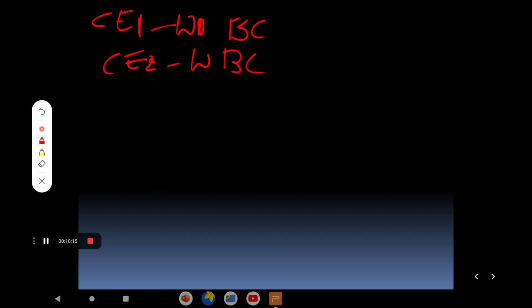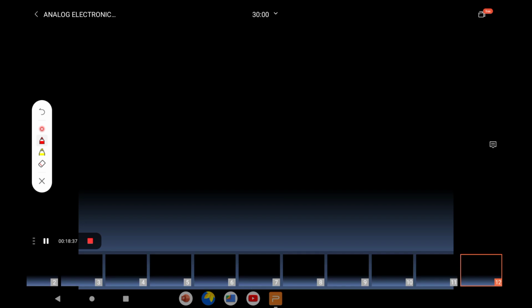The third step is to represent the medium frequency analysis. In medium frequency analysis, you simply short the capacitor values and the supply voltages to ground. Then you can represent the circuit diagram as the equivalent circuit, the AC equivalent circuit, also called the small signal model of the corresponding transistor. For that purpose, I have to draw the complete diagram.